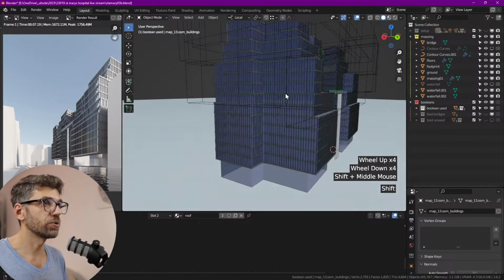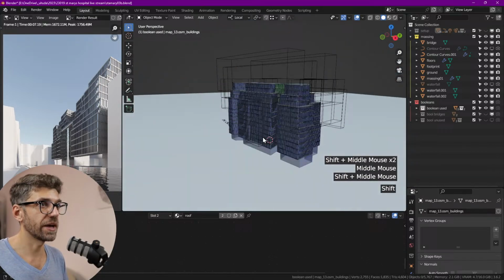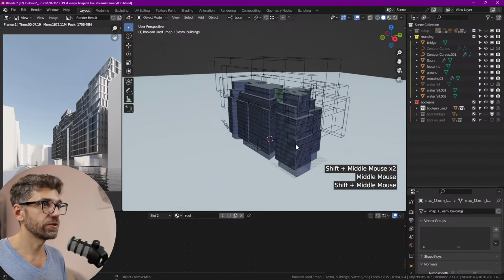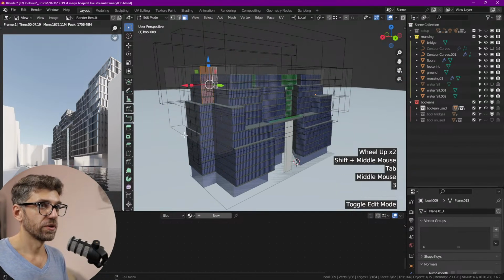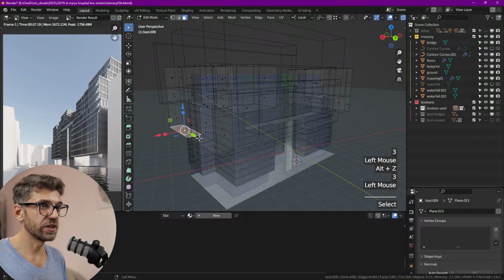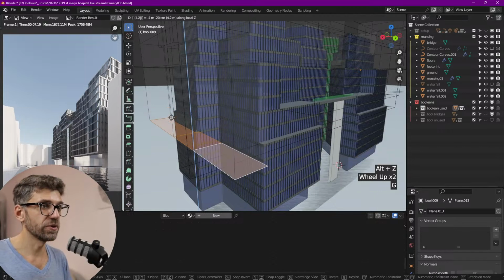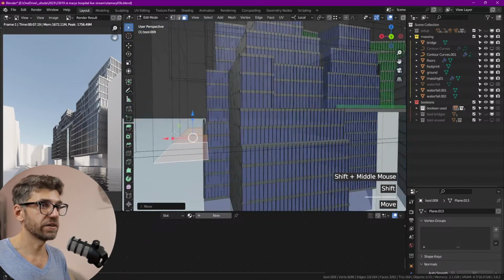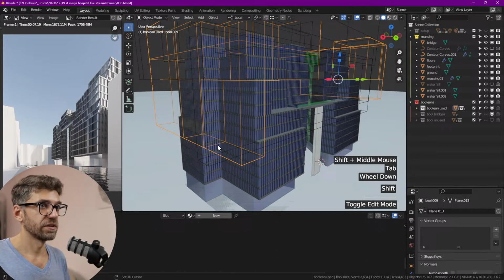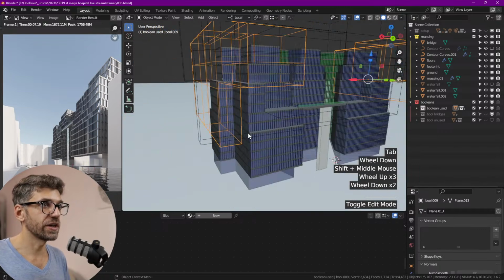I think that might be a good thing to do around, except I'm noticing that this level of setback and this level of setback is not quite the same. And it's okay because it's just a very simple element. In here we have to grab these faces and move them one floor up. So G is at minus 4.2 and that should give us the right setback, right? Yep. And now we want to create just another setback over here.